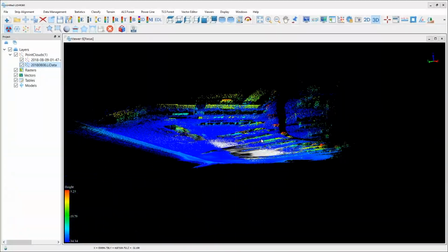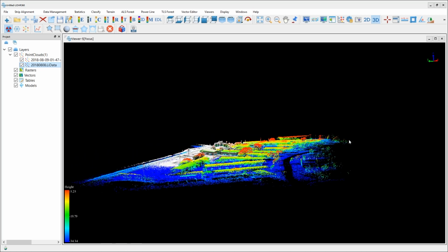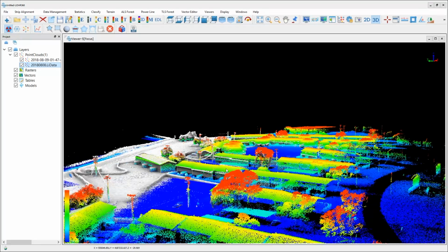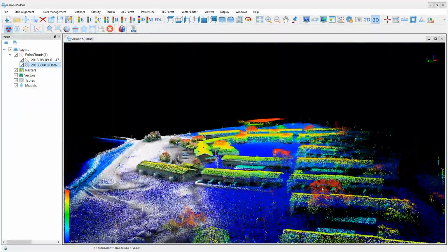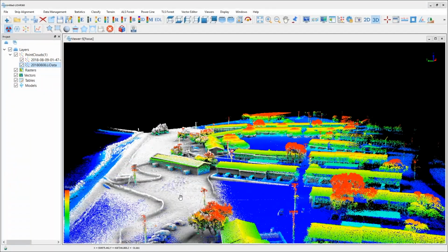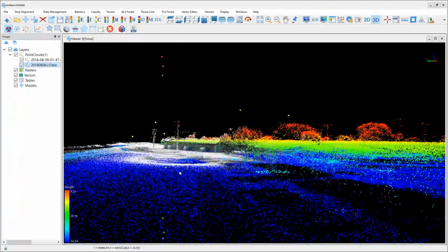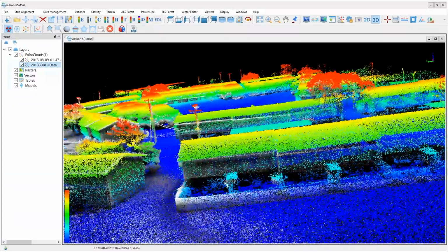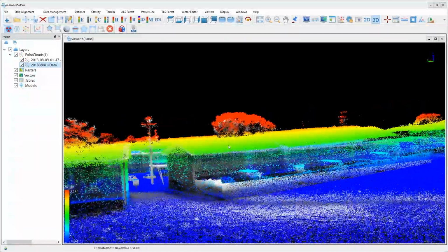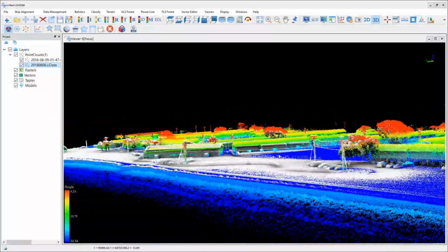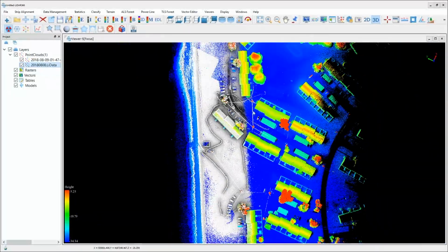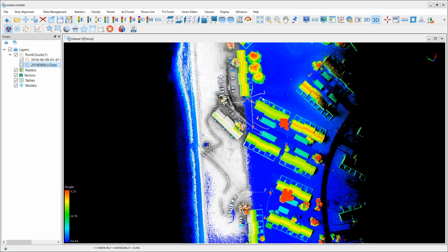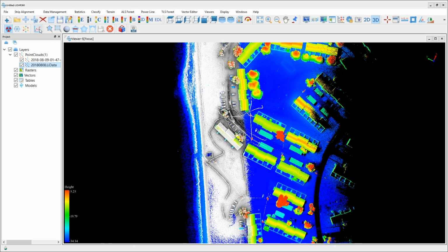The area in white-ish gray is the LiBackpack data, while the area that is colored from blue to red based on maximum minimum elevation values belongs to the UAV LiDAR. You see that in portions of the alignment the gray area sits well above the area which is colored, or the UAV data. This represents a poor alignment, meaning we should probably go through the rectification process again and choose new matching point pairs that will give us a better alignment between the two data sets.